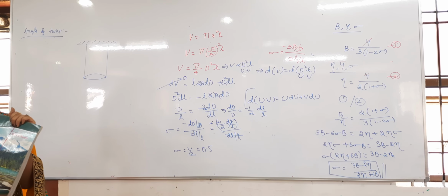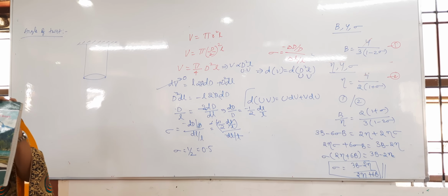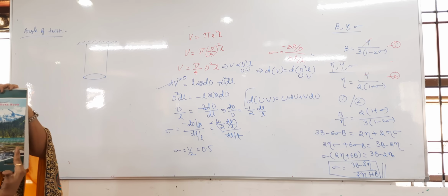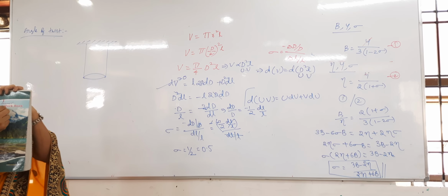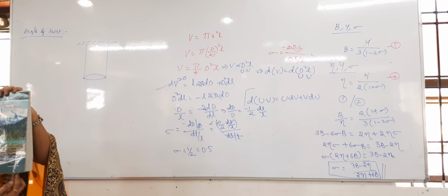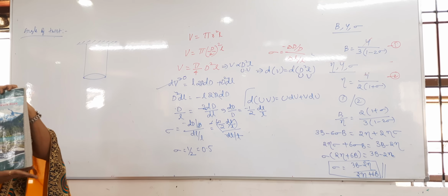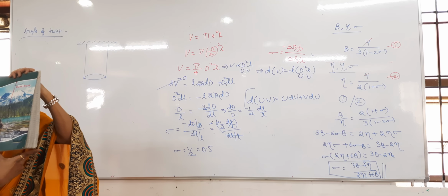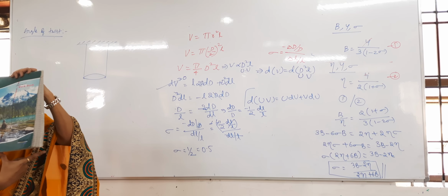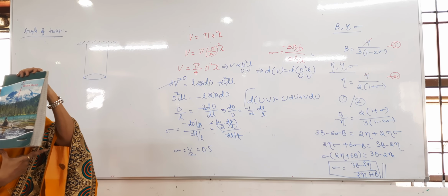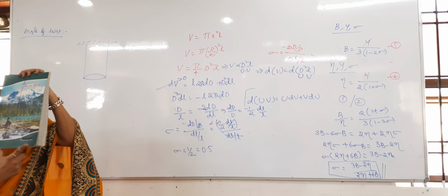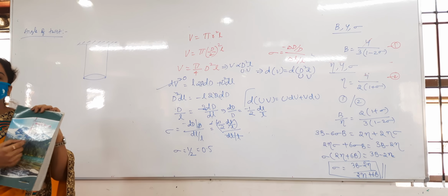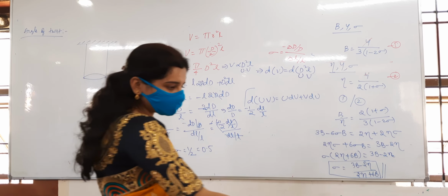Clear? If any circular rubber like that is there, I can show you easily. But here you can at least assume a little bit. This line is displacing like this, correct? So which angle is that? Shear angle. This point is displacing from here to here by gaining some angle. See my fingers, whenever I hold like this and twist, this end is fixed only. As I twist, this forefinger also displaces by some angle. That angle is the angle of twist, and this other angle is the angle of shear. I will draw it in the diagram, then you can understand.